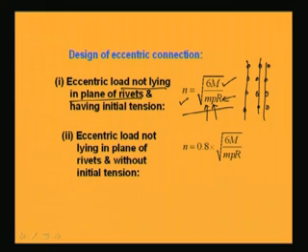So, in this way we can find out the approximate number of rivets to start with the design. With the assumption of this many rivets we will start design, we will find out the stresses in different ways, that means sigma Tf calculated and tau Vf calculated. Then we will see from both the cases whether it is becoming less than the allowable or not.